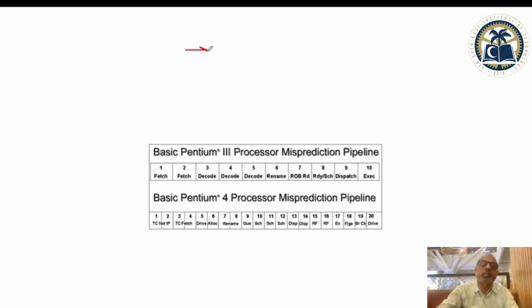So this is the reason, because of the task. For example, in every processor, like a Pentium processor, you take an instruction in the program memory. So this is the instruction in the program memory, and maybe it wants to multiply two numbers and store the value back in the memory. So there is a task which this instruction needs to do. First you need to get this instruction from the memory, then you need to decode it, figure out what this instruction wants to do. Does it want to multiply numbers, and which numbers, where those numbers are? So operands are fetched, then the actual operation, then does it want to store something somewhere, and then storing.